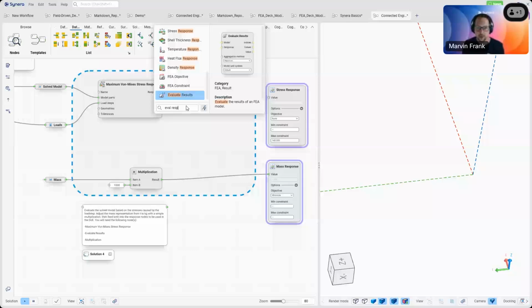Then I do a kind of smoothing here. I want to give it a bit more headroom, so I add one layer more of the voxels. I smooth everything again here. This is a very good basis for our quad mesher, as you have seen before. So that's our nice quad mesh. Then again, I have that robustness filtering to make sure I only have the main mesh, and then the mesh to solid, which gives me the solid.